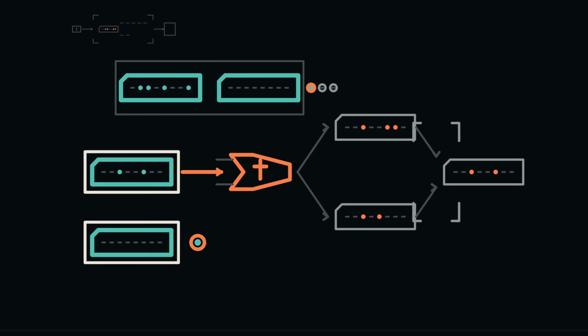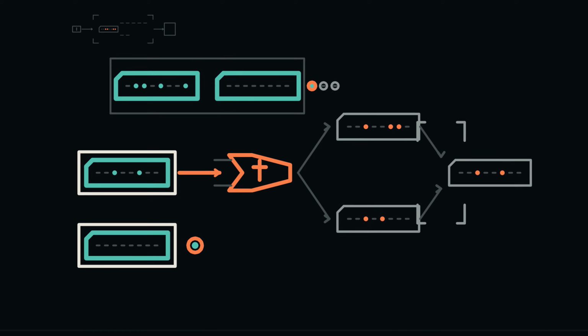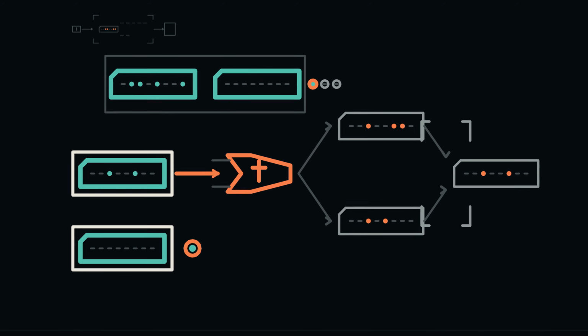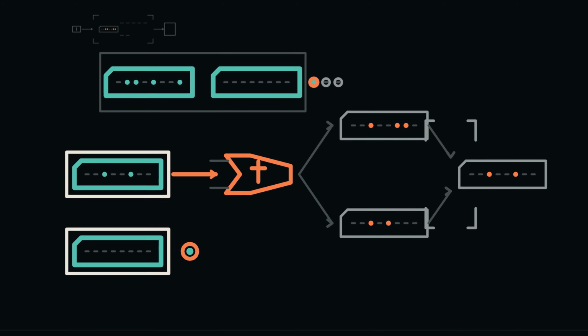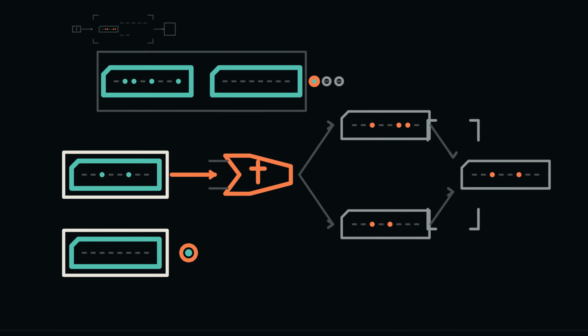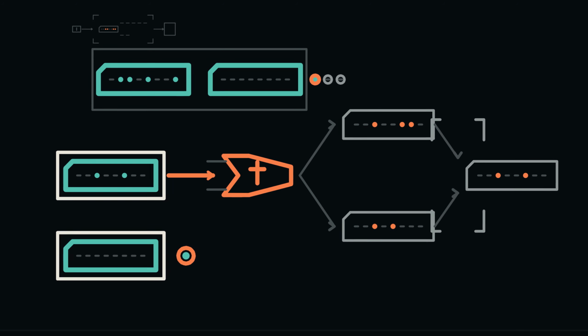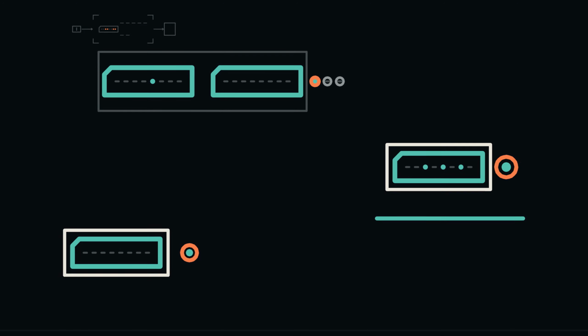Fetching branch if 0 advances PC to 2.6 before execute. Now the condition is true, which next address should commit, 2.6 or 2.8? The target, 2.8. A taken branch replaces the ordinary fall through PC. The jump at 2.6 is skipped because its address is never selected on this path. PC now holds 2.8, so the controller fetches the 2 byte halt instruction there.